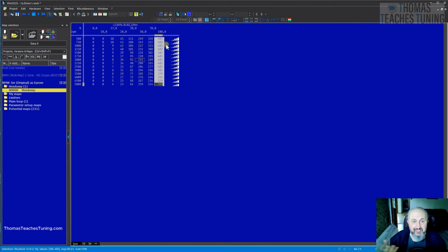So we need to treat these maps as two separate entities of one map while editing them, even though conceptually they function as two separate characteristics. It is one map. This is why I designated it as map 1A and 1B, allowing us to consider them together, understanding that the torque limit could correspond directly to the last column in the driver switch map, the very last column. So at this point, we have established the driver switch map.